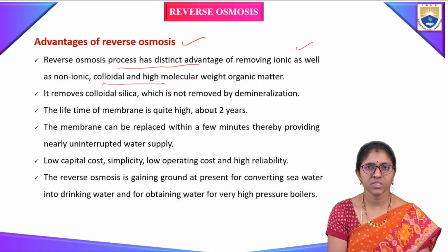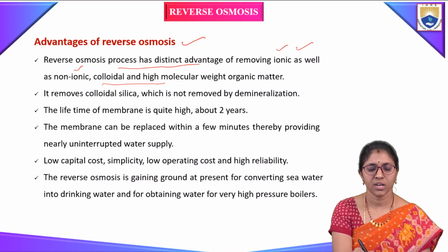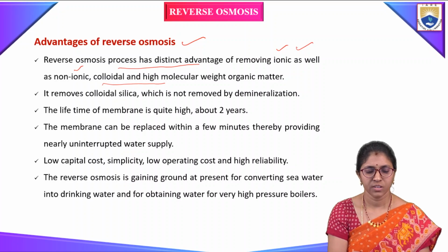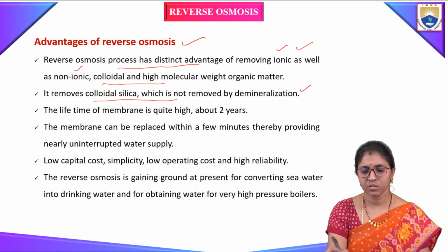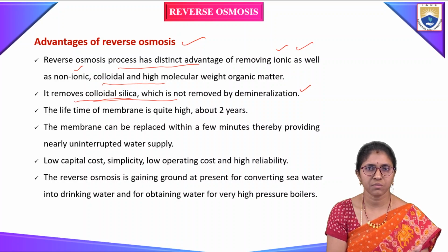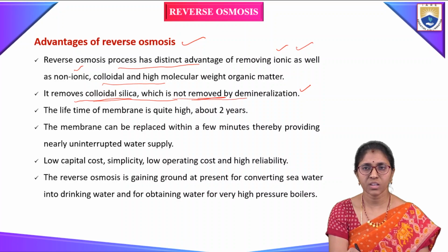It removes colloidal silica, which is not removed by demineralization. So here we remove the colloidal silica by using reverse osmosis.